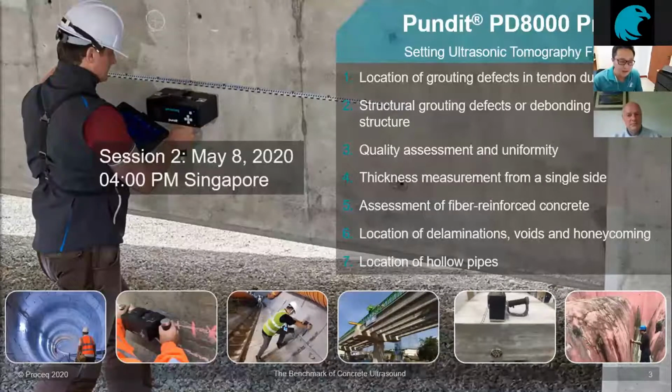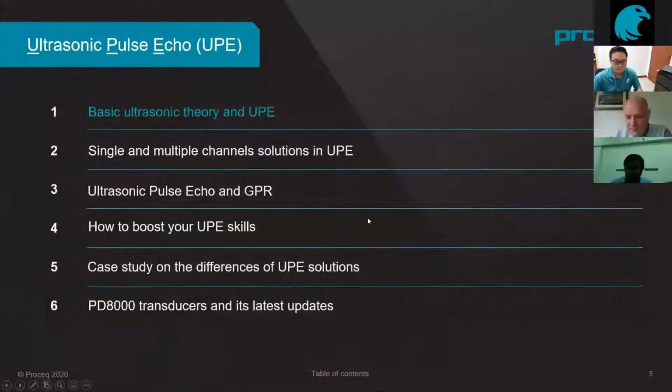We already have many interests in structural safety, durability, and performance, right? So we need an efficient system for early or regular structural assessment, as well as quality assurance. As one of the most popular and best solutions for detecting flaws in concrete, I think ultrasound Pulse-Echo methods should be considered for your first choice. You should consider or apply this kind of testing not only for new construction, but also for existing buildings. So we can have a quick look at the Friday topic here.